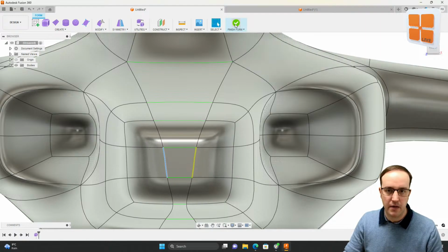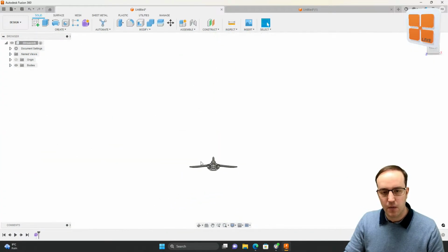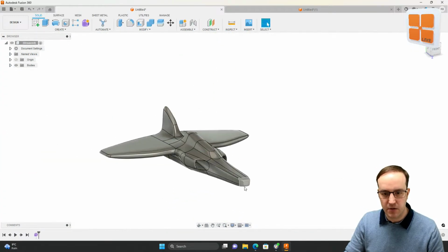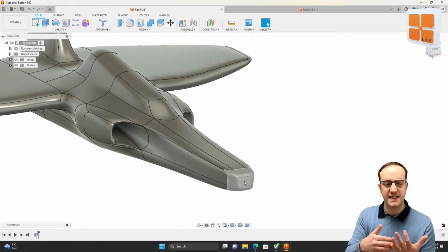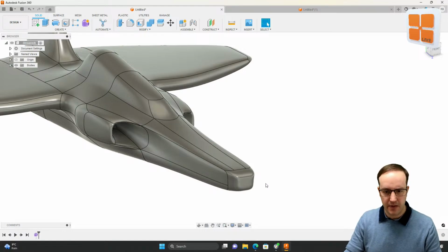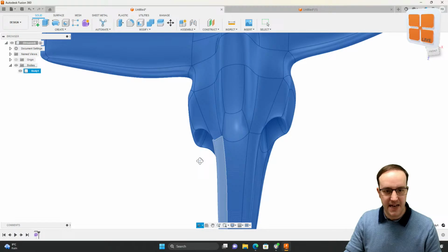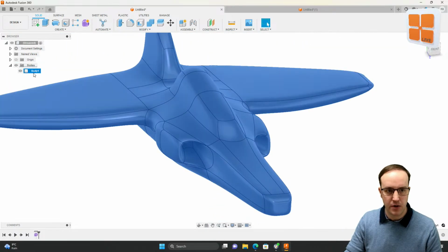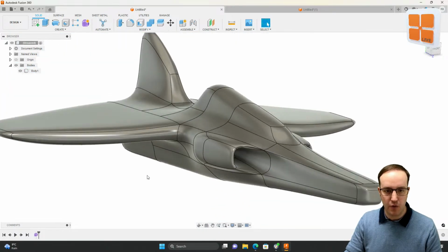Try and get it to come out of the form. There we go. So when it comes out of the form, it tries to turn this into a mesh. If you've got things like self-intersection or overlapping, I had those two faces too close and curved next to each other there, so they'd have been overlapping or self-intersecting. We basically end up with a standard body like we have in Fusion. That body can then be used for anything else.